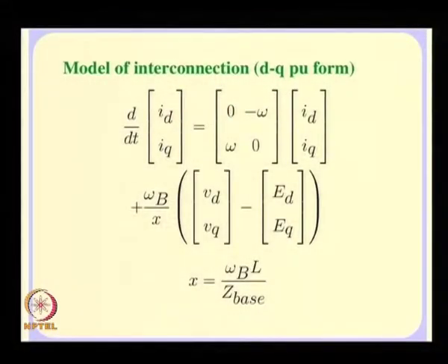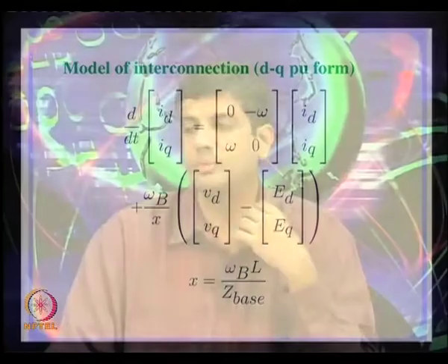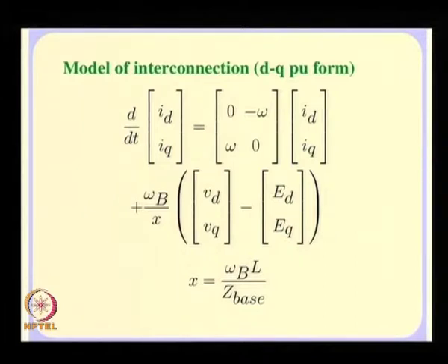Now, if you look at what will happen in case you try to transform this into dq0 variables, transforming to dq0 variables is quite simple in this case. We have talked about the dq transformation, or the Park's transformation. If you use the Park's transformation, you transform IA, IB, IC into ID, IQ and I0, and by doing that the equations are quite straightforward, but remember that you get these speed terms, or omega dependence. Omega, remember, is d theta by dt, where theta is the instantaneous position of the rotor of the machine. So, if you do the dq analysis of this system, you can express this equation in this fashion.